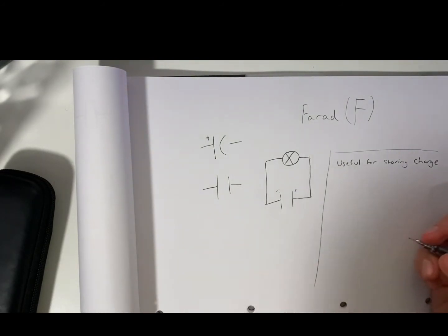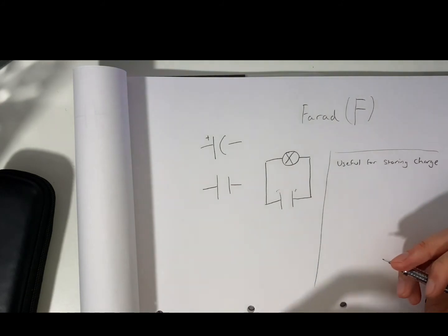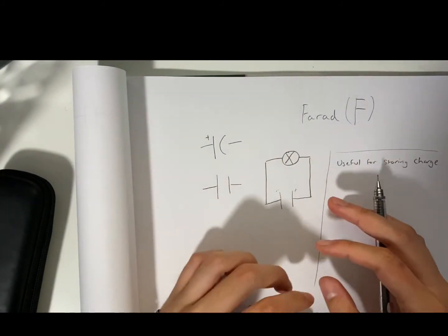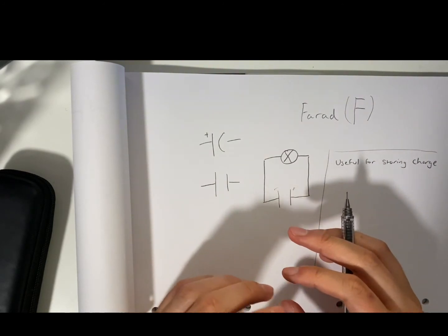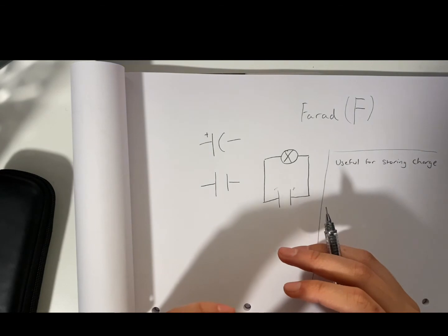I'll just briefly explain that. A decoupling capacitor, otherwise known as a bypass capacitor, stores charge and provides power in case there's an input voltage drop to an integrated circuit, an IC. This is why in your circuit diagrams you may see them as close as possible to the voltage in pins, and this allows them to provide a nice steady voltage.